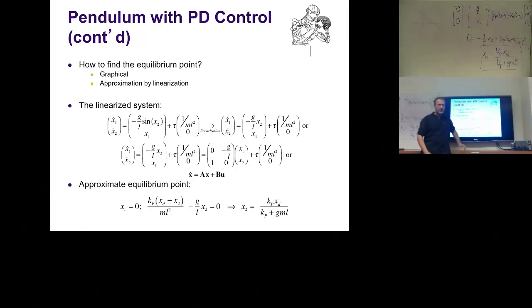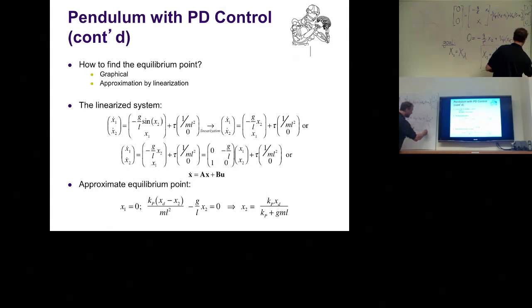And one thing to notice, now going back here to the big equation, that's why I wrote it in very big terms, so I hope you can see this nicely. Our goal was, remember, that x2 equals x desired. That was the goal of our control. Now, this is not what we got, okay? x2 equals all kinds of stuff, multiplying times x desired. We can make this a little bit clearer, actually taking the x desired as a multiplier out of this fraction. So essentially, x2 equals x desired, but there is a pre-multiplier, which is annoying.